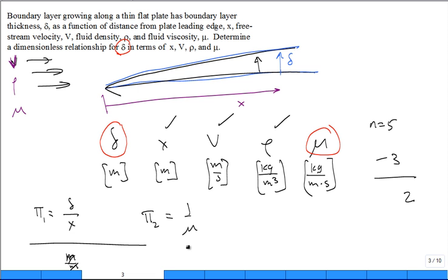I don't know, but I'm anticipating a Reynolds number. The Reynolds number, rho v d over mu. So if I'm going to start with a more complicated parameter, viscosity, I can put it in the numerator or denominator of my pi group. I'll put it in the denominator. I may not get a Reynolds number, maybe I do. Can you see why I'm starting that way? Because mu is in the denominator of the Reynolds number. Otherwise, I'll develop the inverse Reynolds number as a dimensionless pi group.